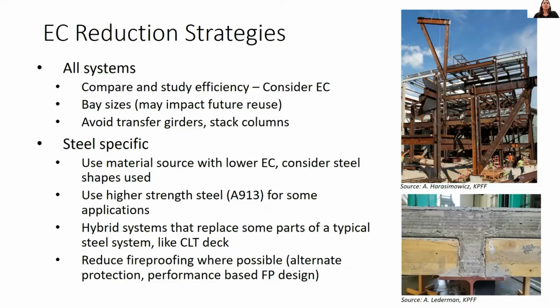So are there possibilities for taking, say, your metal deck system out and replacing it with a CLT system? So preserving the long span greatness of steel, but using something else to replace part of the impact. And the other thing with steel to always think about is the fireproofing, right?